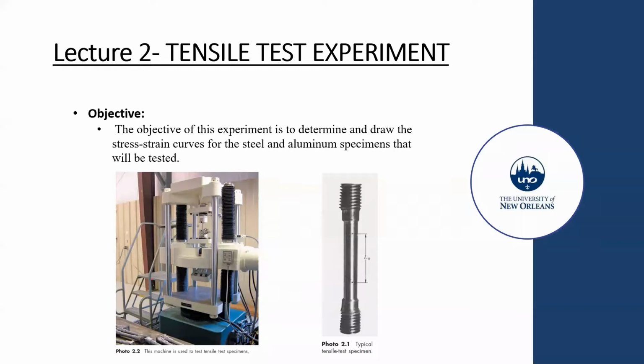Right. If you are on the design stage, if you are designing, let's say, a beam or girder or column, first you want to know how much load you can apply to this member before failure. So you want to know what is the maximum stress that you can apply to this specimen or to this girder or column. In order to know how much stress this specimen or the element can take, you should test it before you use it.